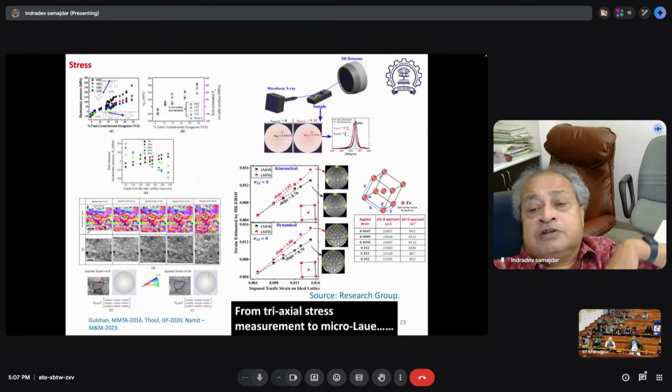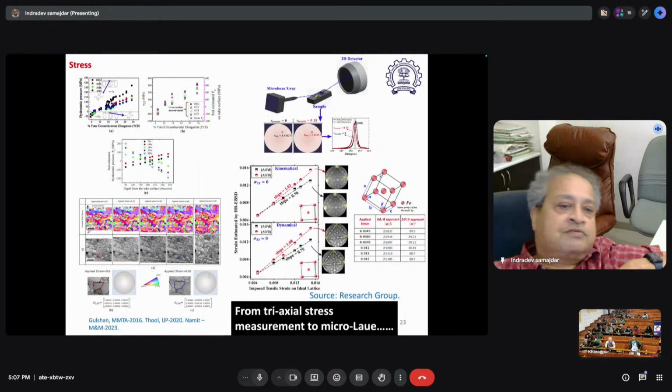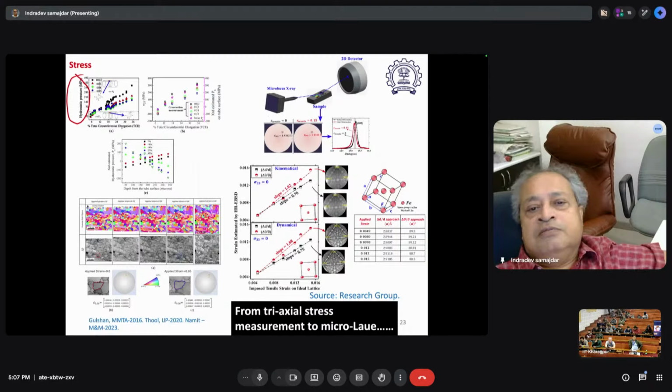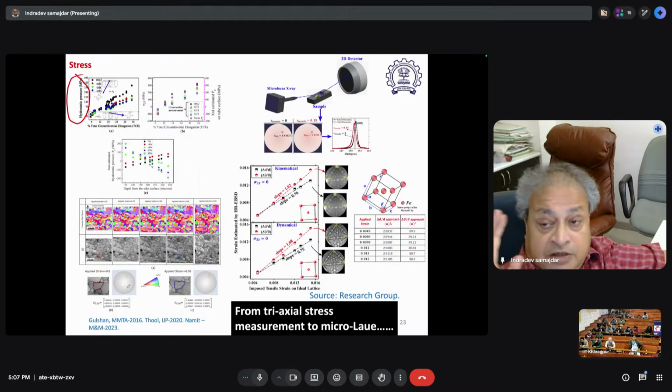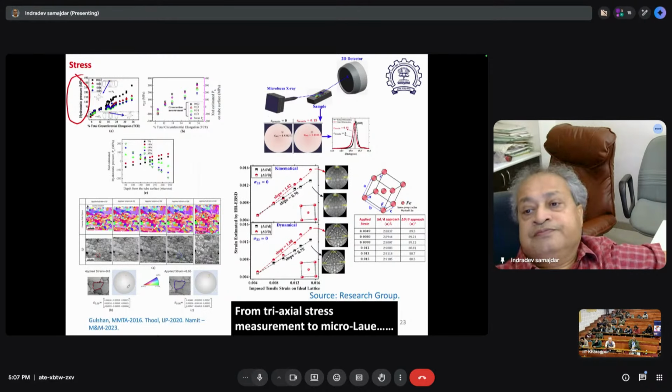You can measure, and this is non-trivial, track shear residual stress, and more importantly, the hydrostatic stress by XRD. Non-trivial, but absolutely beautiful. You can do a tensile deformation and track the development of residual strain. Remember, by these diffraction-based techniques or any technique, you only measure strain. There is no stress meter. You can do all this.